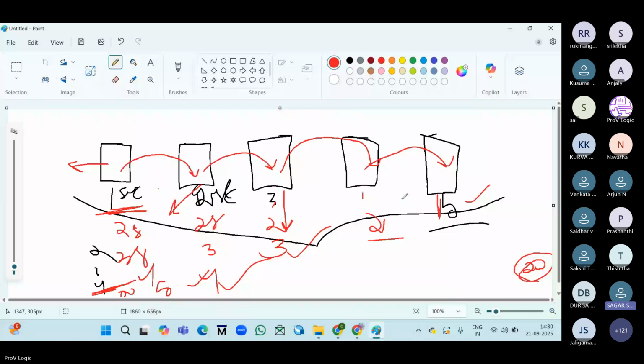Since they are stages, how are these stages connected with each other? Of course, there will be connections. There will be some signals connecting these stages. The output of one should get to the next, and there will be some stages internally. This is exactly what we are doing in the project. In our curriculum, there is a RISC-V processor project. We are going to design the fetch stage individually, the decode, execute, memory access, and write back stages, all hardware individually, and then the top level connections, and then SystemVerilog verification.